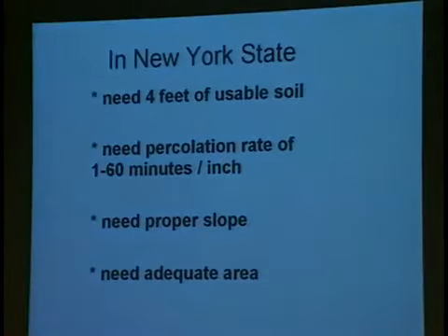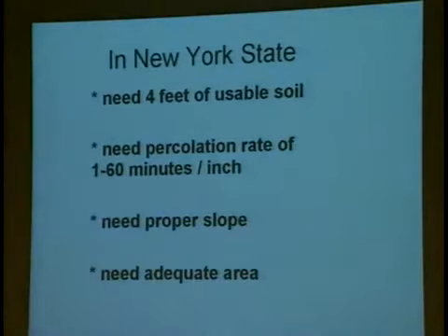Okay, again, in New York State, you need 4 feet of usable soil for a conventional system. You need a percolation rate of 1 to 60 minutes per inch. You need proper slope. You need adequate area.